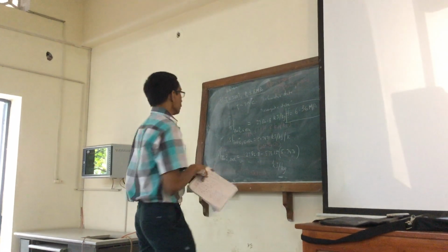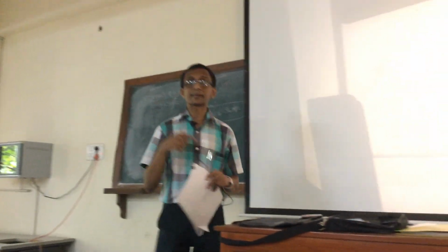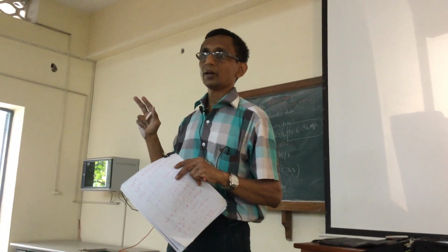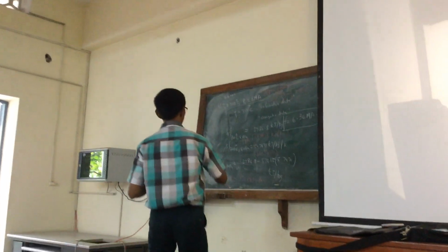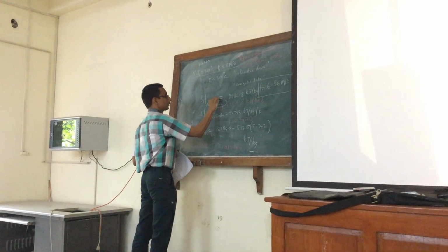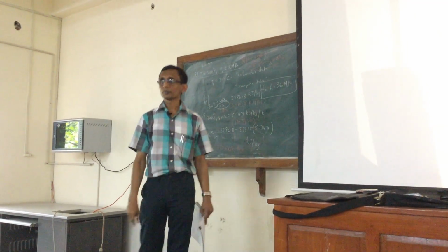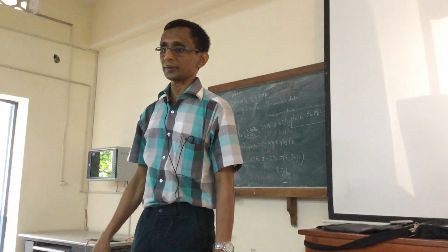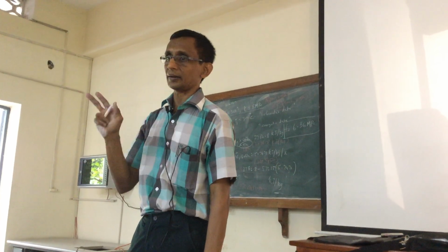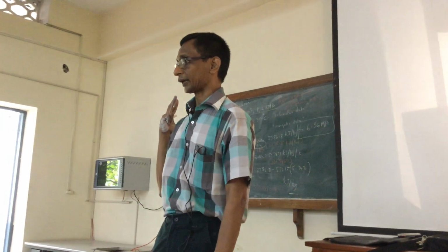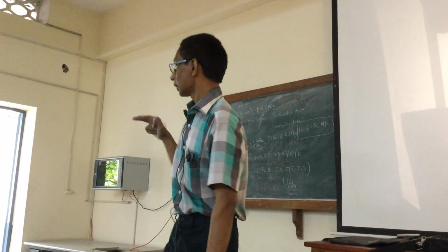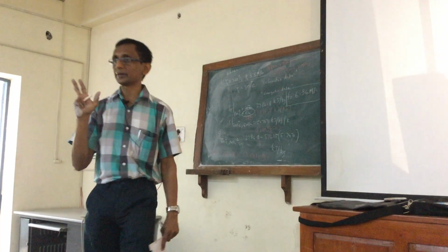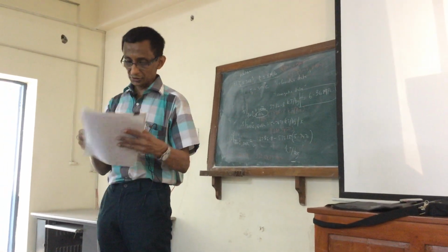Right? So now the next question Sandler has is to calculate the saturation fugacity. Now the saturation fugacity proceeds in the same way. Only instead of the values at 8 megapascal, obviously I want at 8.6 megapascal. If I wanted to use the integral of B minus RT by P, I would have to go further down all the way to 8.6 megapascal, but I am not going to do that because that involves an integral and recording so many B values, and this is more direct. So it's very straightforward. The lower pressure data remain the same, but instead of 8, I need the data at 8.6, the saturation. So you can calculate the saturation fugacity.